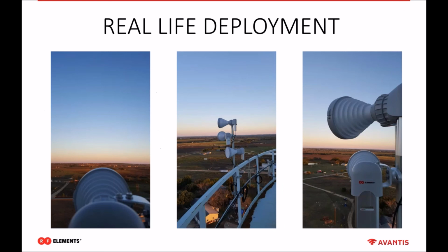I would like to show you an installation from real life, how the scalability can look. These guys in Texas had a 90-degree sector with a lot of customers there, and basically they were not able to connect more customers. So what they did, they took down the 90-degree sector antenna and mounted on such a pole 3 symmetrical sector antennas.